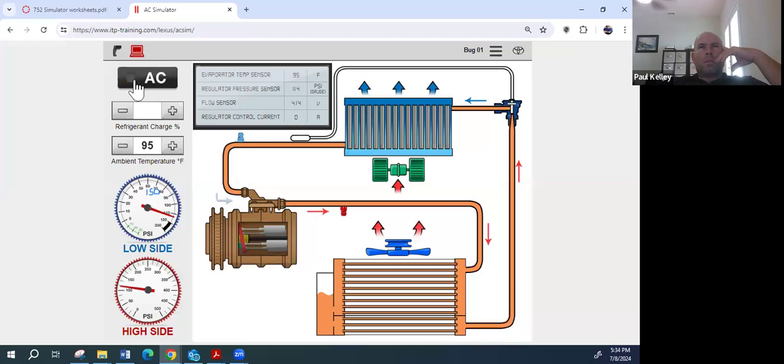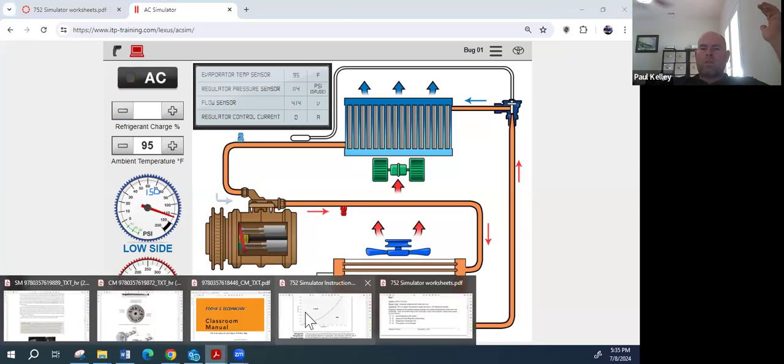But does anybody notice something here? What's happening here? The green AC light is flashing. That's interesting. Did you guys learn about that in the reading a little bit on the Toyota manual? A code would be on a new system, yes, but on an older system before they set DTCs, this was more of an indication of a fault. This is saying there's a problem in the circuit with the AC compressor clutch. We don't know exactly where in the circuit, and unfortunately can't do voltage readings. So we've done as much diagnosis as we can.